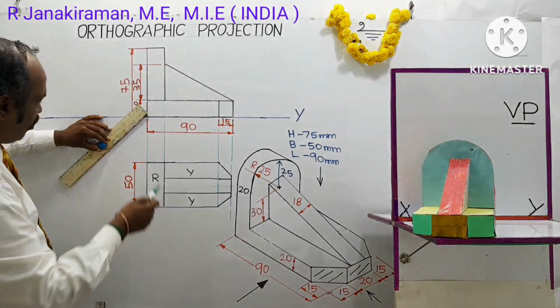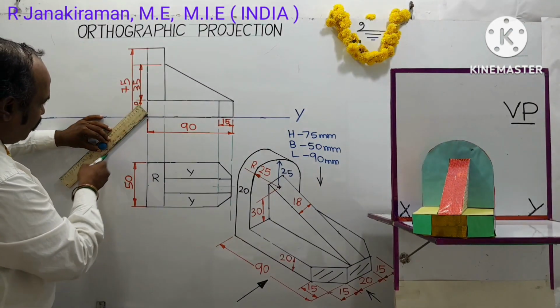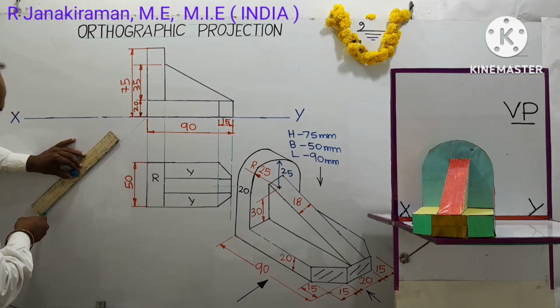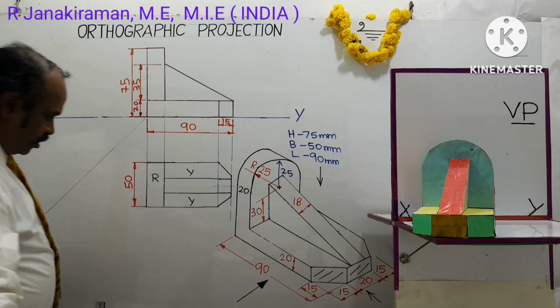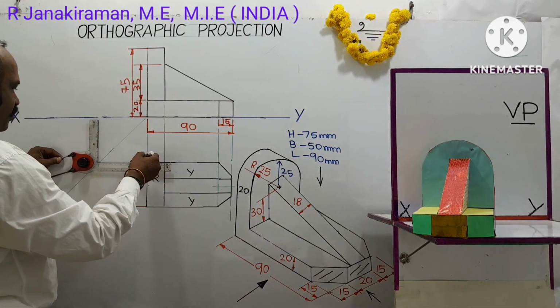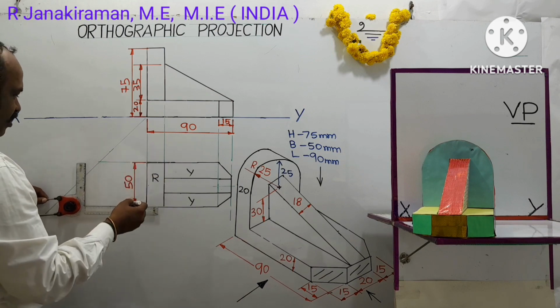This line shall be drawn by using 2H pencil. It's a reference, it's called as miter line. Understand? Next, you draw horizontal projector from the previous top view using the longer scale of your drafter.